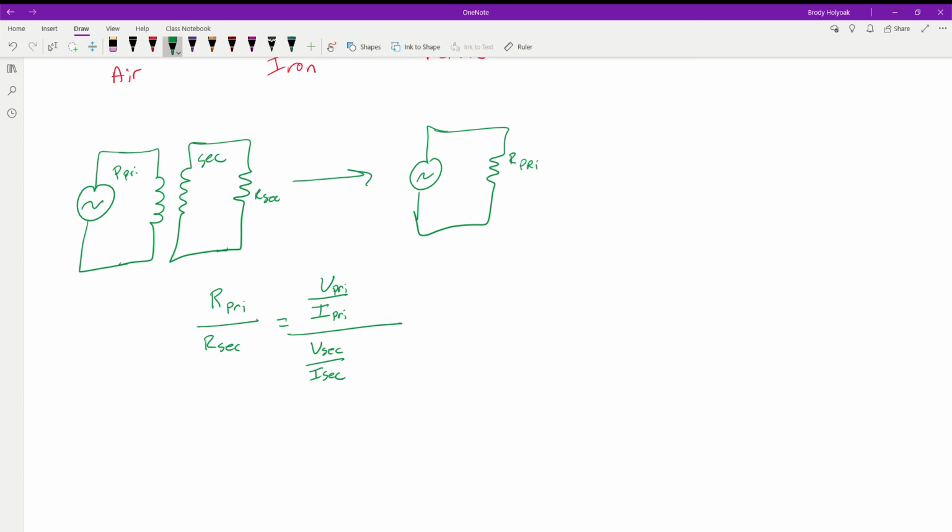If we have more resistance on our output than our input, we're going to see a decrease. It's going to be more like a bell curve. Right here in the center of this curve, this represents power, not R. This represents our power, and this is our resistance. Here is where we're going to have the most power. So power is going to be greatest when our load and our input are equal to each other. That's when we're going to have the highest amount of power.